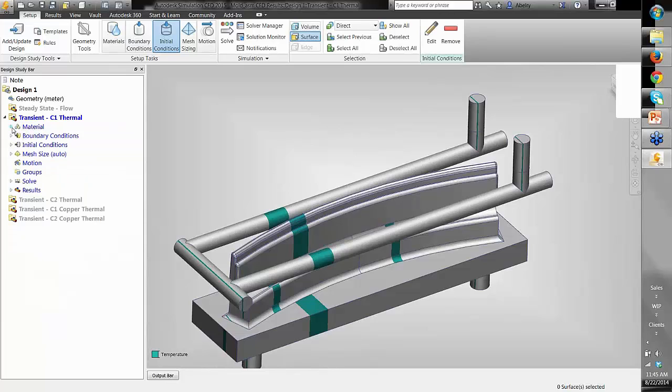Another thing that we're able to do with CFD is solve for the flow properties first, and then once we know how the flow moves through all our flow channels, just clone these runs and solve for the thermal properties by themselves in a transient manner. So we're able to decouple the flow and thermal solver, and that's really important because the flow solution takes about an hour to solve, but the thermal solution over a 30-second cycle takes like 20 minutes.